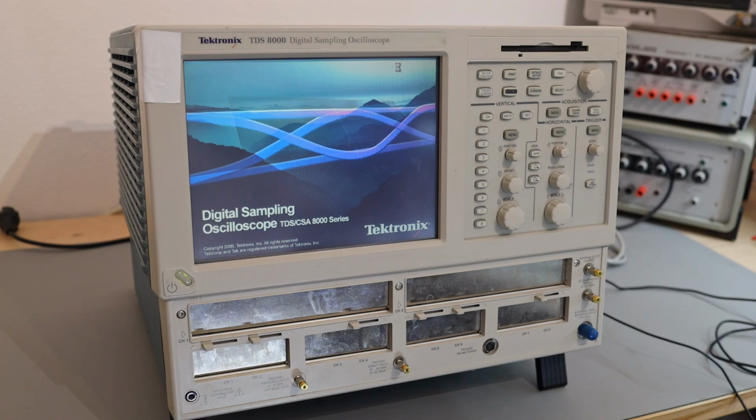And this specific oscilloscope is meant for a really special purpose. They are meant specifically for signal analysis. For example, eye diagrams, jitter, rise times, and TDR analysis. And they are also meant primarily for communication systems, and you can also measure with them the impedances of traces, of cables and everything else. You can definitely do really good TDR.